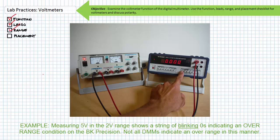If you were to accidentally have this meter placed in the 2 volt range and measure something close to 1000 volts, it could not measure it because it's out of the meter's range. If you were to accidentally interpret this over-range reading as an indication of 0 volts, you could expose yourself to potentially deadly voltage. Use the function, leads, range, and placement checklist correctly every single time. Use the checklist, think about it, really think about it.